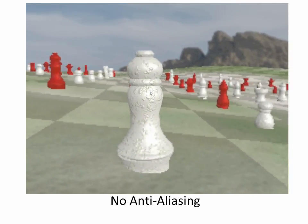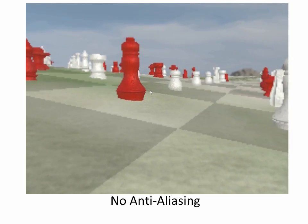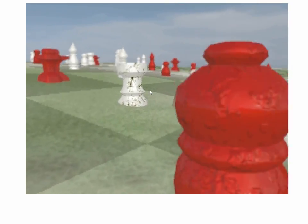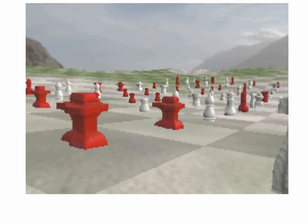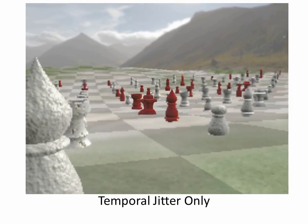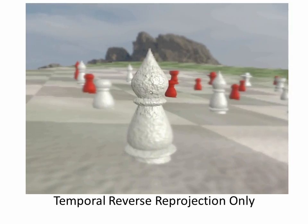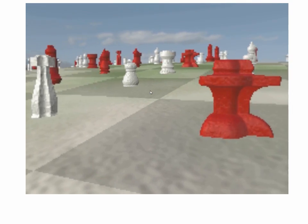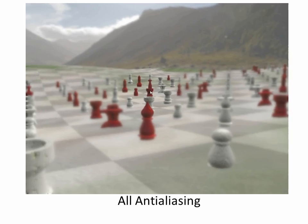With a reduced sampling rate in the periphery, strong temporal and spatial aliasing artifacts degrade the apparent quality to unacceptable levels. We use a combination of traditional multi-sampling, jittering the pixel sample positions, and reprojection blur. The aggregate effect provides efficient yet highly effective anti-aliasing.